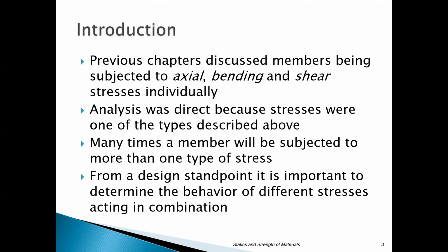Axial, remember, generates a stress along the cross section, and that means the area you're considering is perpendicular to the direction that your force is being applied. Bending stress is based on the fact that you have a bending moment going on. And shear stress develops due to forces that are acting parallel to the cross section.